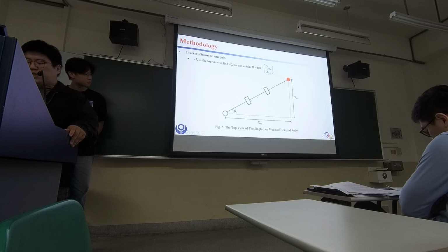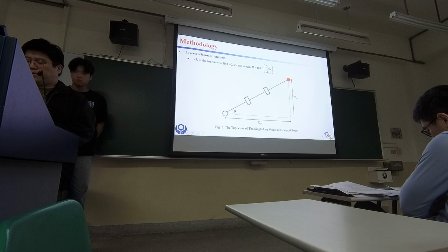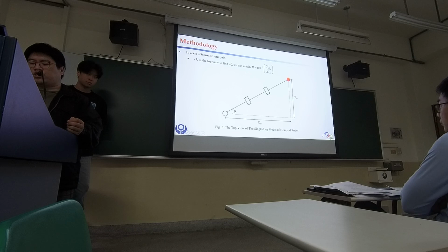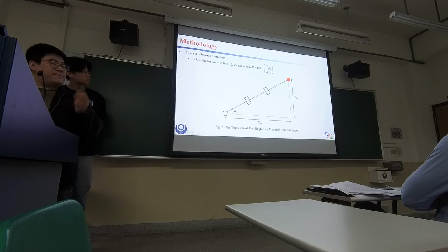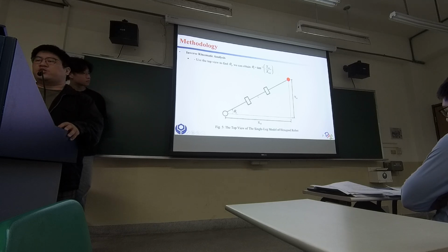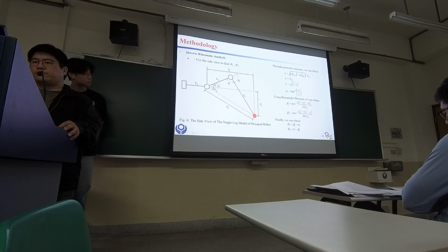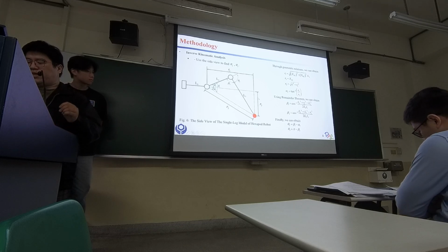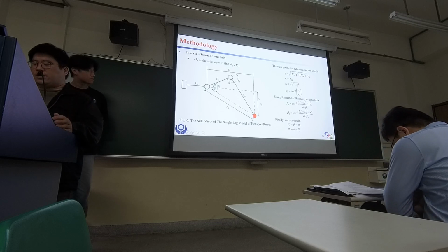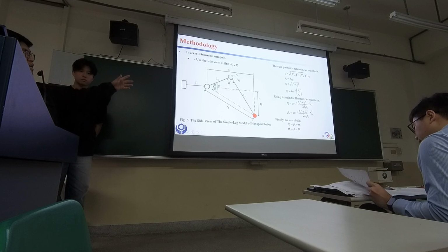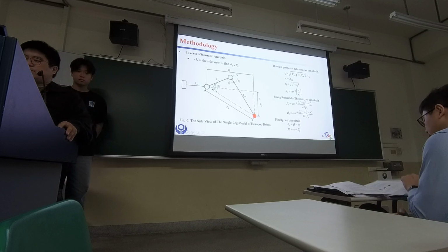We have already initiated a model of the system. From the top view, we simplify the model and use trigonometry to solve the hip joint variable. So we can know how many degrees we need to reach a certain point with the hip joint. And then on the side view, a single leg model is constructed by the position of the end effector. We can use inverse kinematic analysis to derive the knee joint and ankle joint variables.